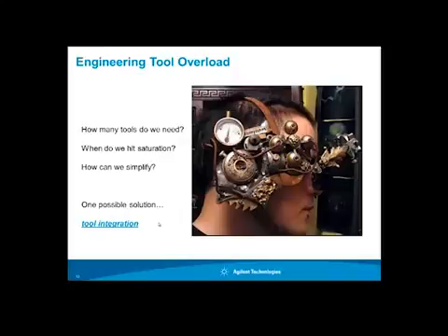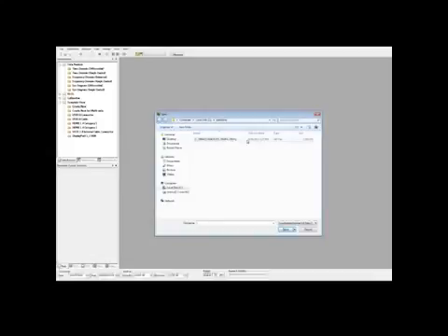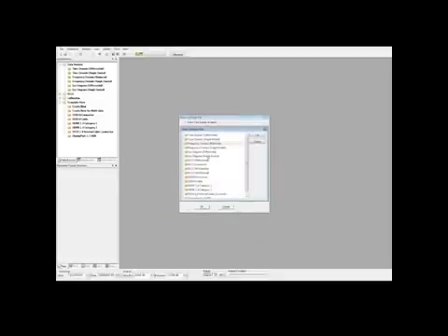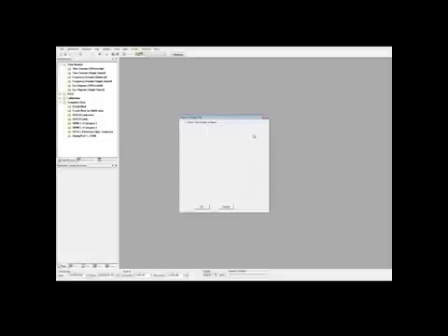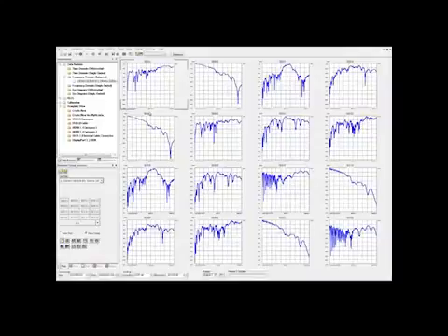What I'm going to do now is spin up PLTS, and when we open up PLTS, I'm going to import a file. Actually, this is the data, excuse me. This is a balanced transmission line from 10 megahertz to 20 gigahertz, and it's a 4-port S parameter file, as you can see here. When I open this in frequency domain balanced, we're going to have those 16 differential S parameters that I spoke about.